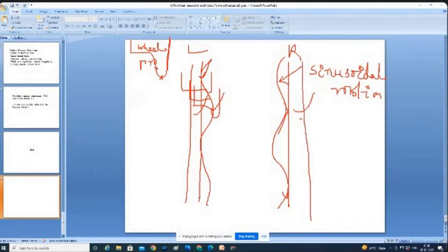This sinusoidal movement. So due to this sinusoidal movement, I told you, whenever this side is touching, you will be getting 3 points of contact. Whenever this side is touching, another point of contact extra will be there. That is totally 3. Okay. So that is thread contact, flange contact. Similarly here also only thread contact in this area. So these contacts will keep on moving like this, either this way or reverse. Anyway, it will keep on moving.